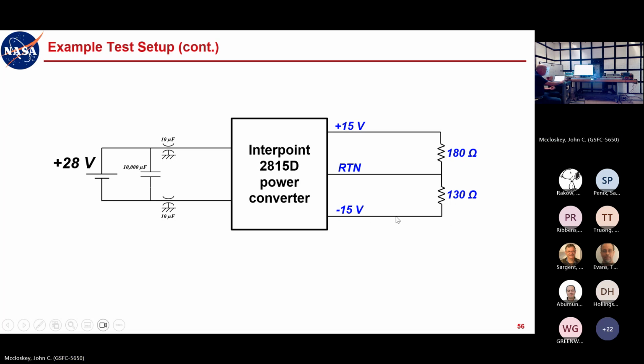So at the EUT, or at the direct output of the converter, you basically have the most capacitance looking out this way toward the load. There's the most capacitance between this point and the ground plane. So you're going to see the maximum current flow across that total capacitance to the ground plane to come back.